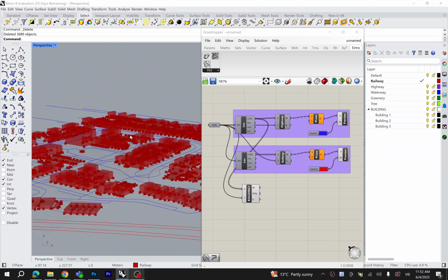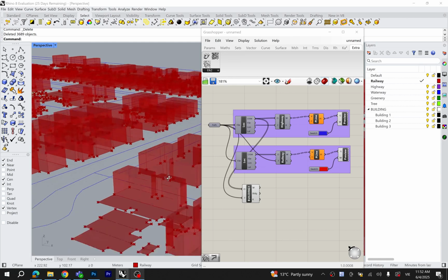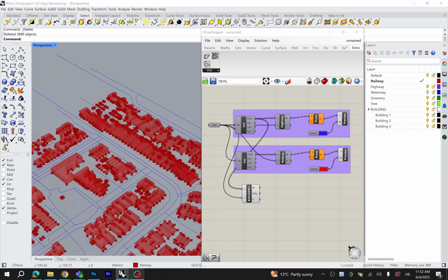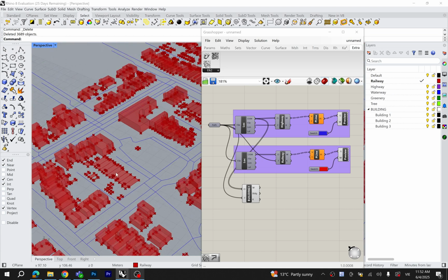As you can see from the viewport, not all the building footprints had height generated. Some are represented on a flat surface, and it's because OpenStreetMap collects data from online users. So when they draw the building footprints with the height number, it will automatically generate in 3D height, and for the others it's just represented in a flat surface.